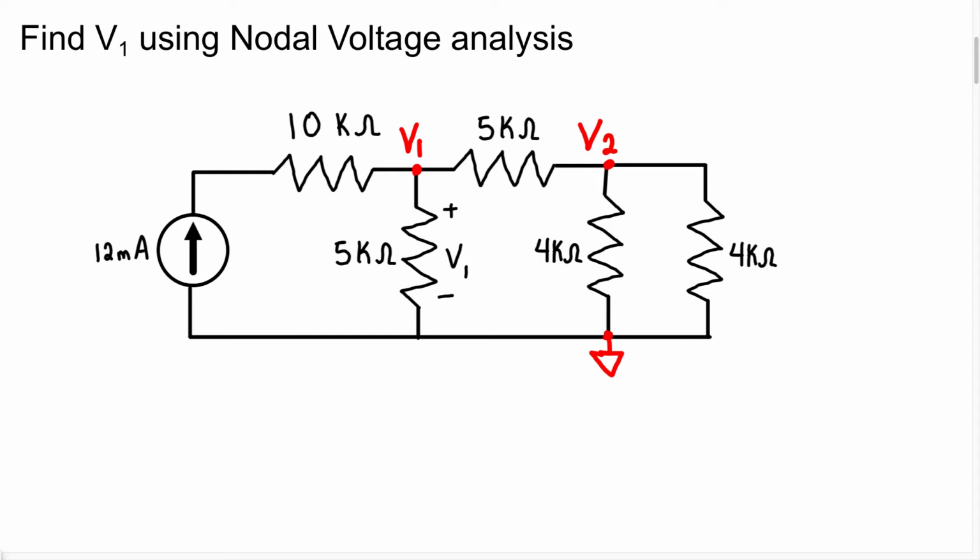Remember a few videos back, we talked about Kirchhoff's Current Law. We know some current was entering the node, some current was leaving the node. But in the node voltage technique, you must always assume that the current is going to be leaving that node. It doesn't have to be so, but that's what you have to assume to get these problems correct. So let's start to work some problems, and then we'll continue from there.